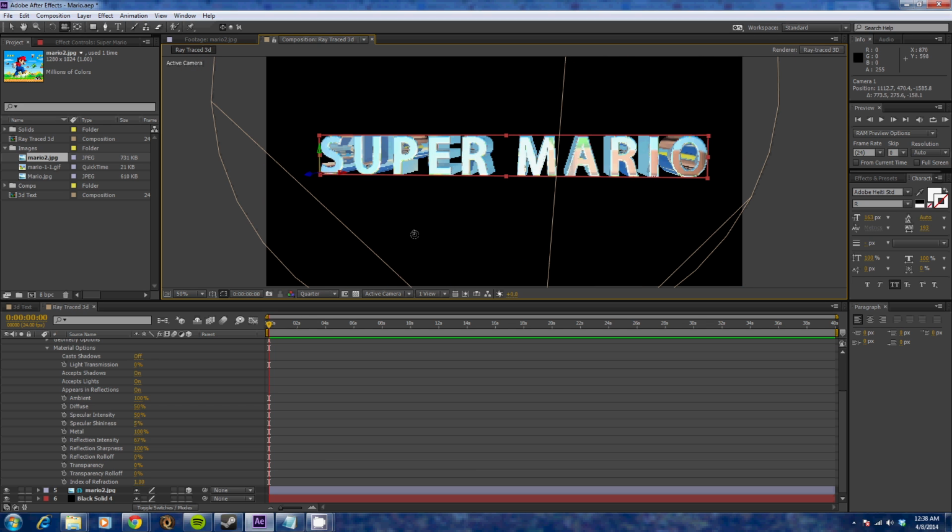And what you can do is start keyframing different movements in light or your background image or your camera to start making cool effects. And you can go through these material options and actually change how the reflection works. You can use the specular intensity to work with your light source and how much that's going to do for it.